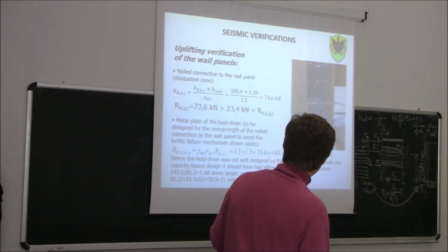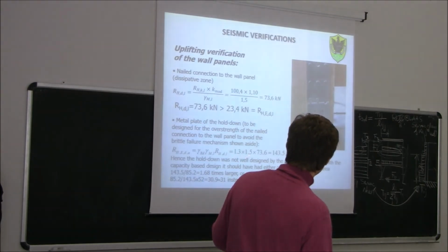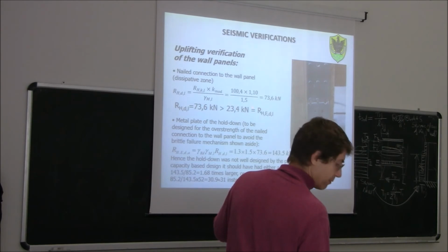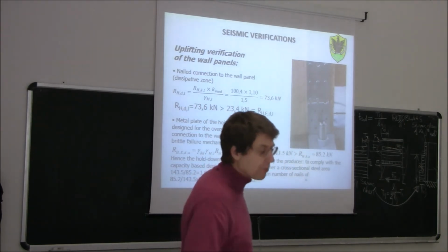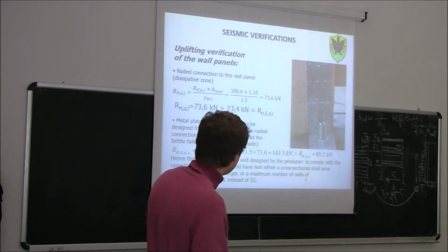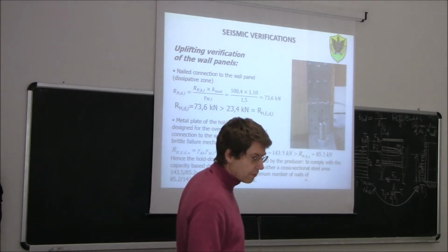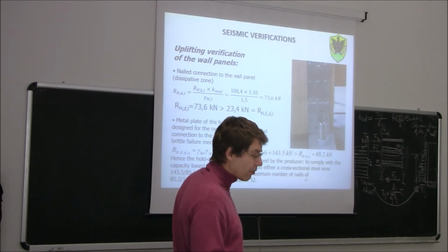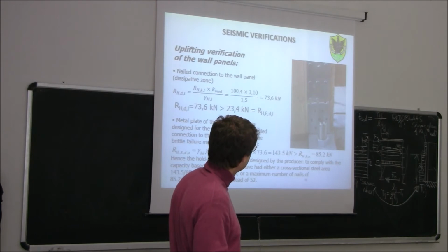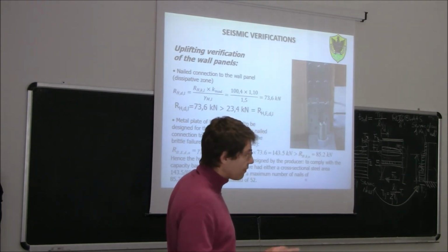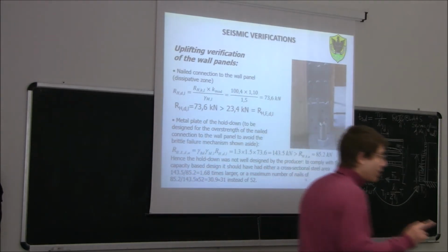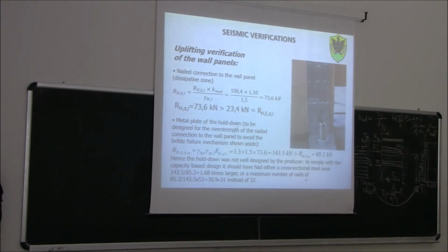In this case, too, it is 1.5. Which one? 1.3? No, 1.5. This one is the partial safety factor. According to the new regulation, this would be 1.45 instead of 1.5. No, strictly speaking, there is a difference. Actually, you're right, because the new regulation has changed the material partial factor for cross-lam. However, the material partial factor for connections is exactly the same. So what does it mean? That what I told you before, the 1.45, is not true actually.